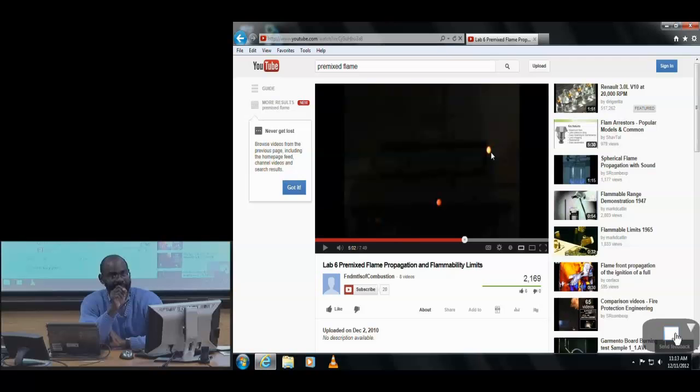chemiluminescence from the CH stretch. So it's the carbon-hydrogen bonds that are stretching that we're actually going to see, and that's going to be the marker of this premixed flame as it goes into the reactant stream. Now, as we go towards the flammability limits, the flame velocity, the flame speed, goes smaller and smaller, and all of a sudden it starts to compete with what you might get from buoyancy-induced velocities in this system.